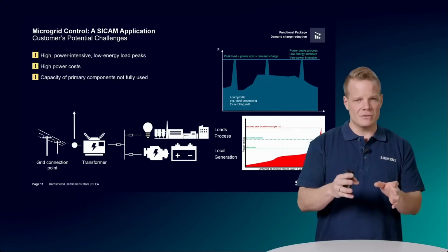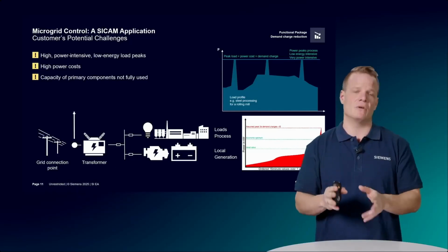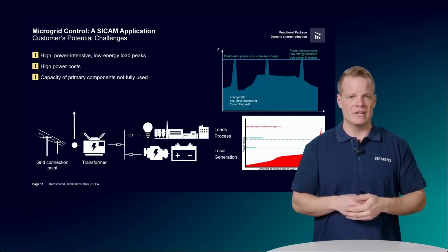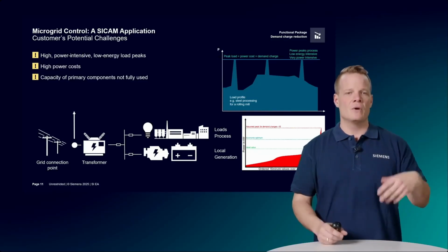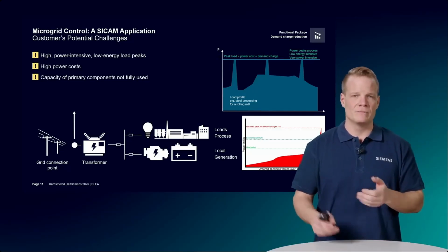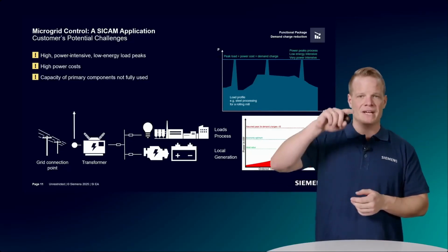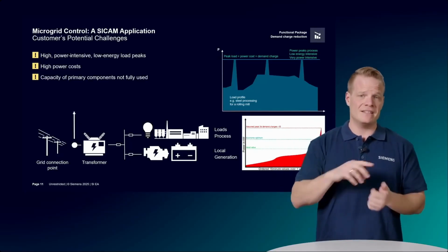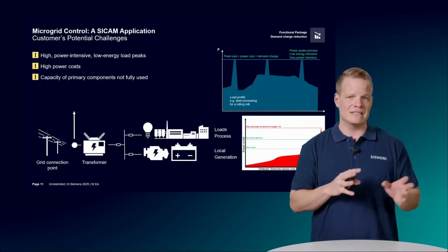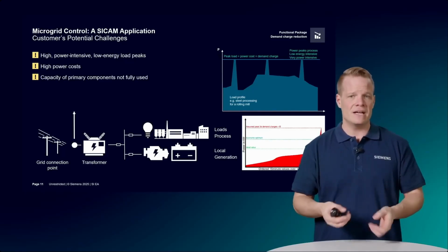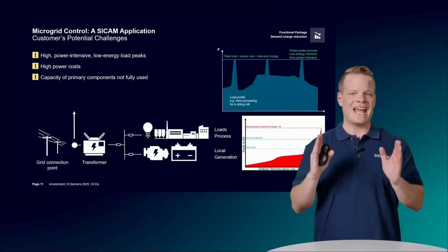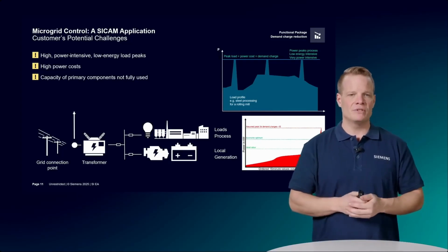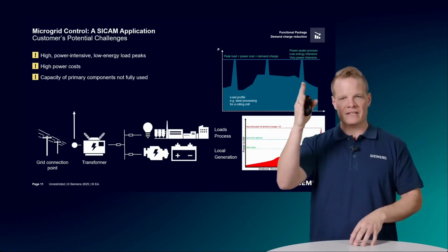So your DSO is measuring 15 minutes of your power consumption, calculating the energy amount of it, and with these goggles on, we are ensuring, as you see in this example, to be able to, first of all, predict by extrapolation. So the microgrid controller is extrapolating the real-time load profile to the end of this 15 minute accounting cycle, and by that is able to detect those peaks, like in this example.